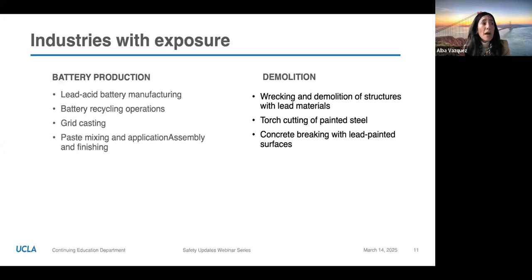If you're going to hire a consulting firm to do this lead compliance written programs for you, don't just rely heavily on them keeping you compliant. After all, it is your job to read those compliance programs and find out whether or not you're doing it right. But with soil especially, you gotta test the soil to find out, because in those sites with wildfires, you will have way higher concentrations of lead in the areas surrounding those sites.